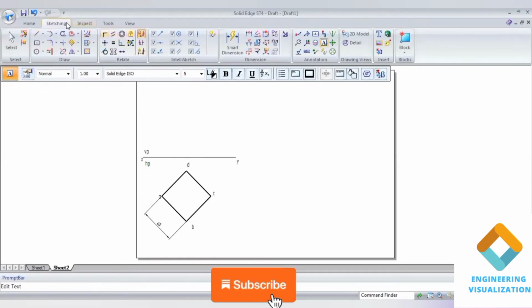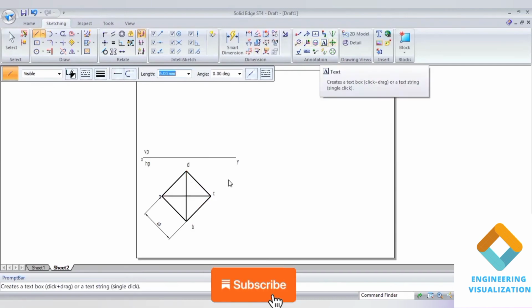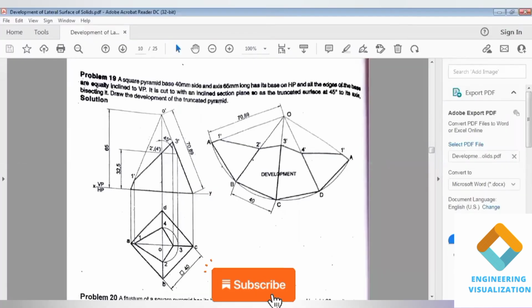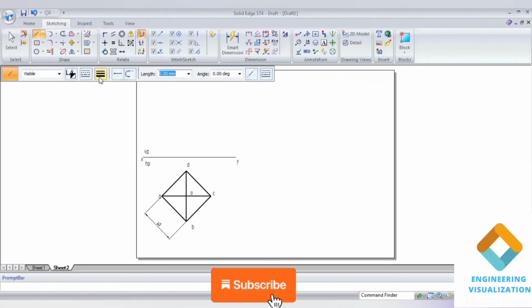Since it is a pyramid, that means we need to draw the slant edges, that is thick lines we need to draw here. If it is a prism, it should be thin lines. So you all should know this difference. So thick lines we have drawn. Write down O1. Now draw the projection lines upward to construct the front view. So the projection line should be a thin line, that is 0.13 mm. We should take that thickness.